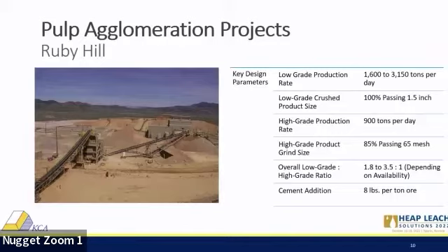The ore was crushed in a 2-stage crushing circuit shared with the high grade ore mill. The high grade ore was then crushed with an additional 3rd cone crusher, followed by single stage milling. That material was then thickened and filtered using belt filters. Again, the filtrate and thickener overflow went to the recovery plant, and the filter cake was combined with low grade ore in an agglomeration drum and stacked onto the leach.